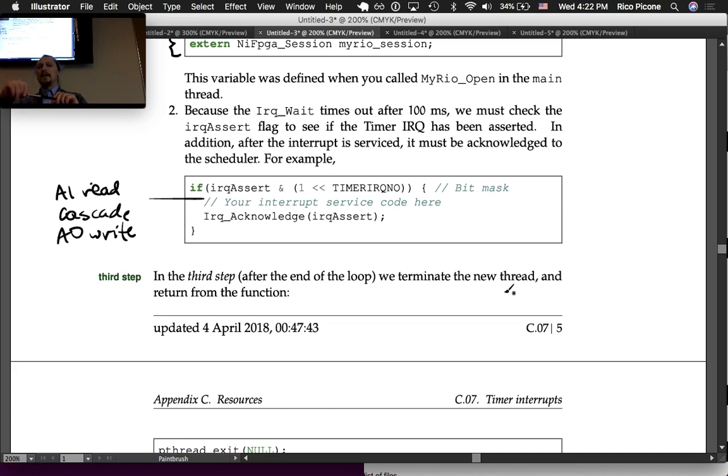So this is definitely a better way to do most things, but sometimes you can get away with just a simple wait function. So we're using Cascade then within the ISR function that we're writing. Yeah, so it's not in main. Cascade is going to be to calculate what Y is right now, based on the A's and B's, based on past values of X and Y. So we're writing three functions: main, Cascade, and then ISR. Yep.